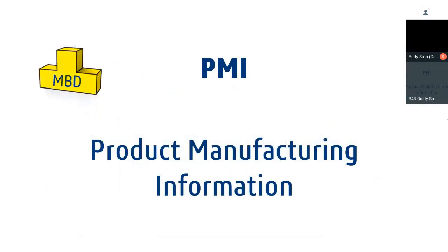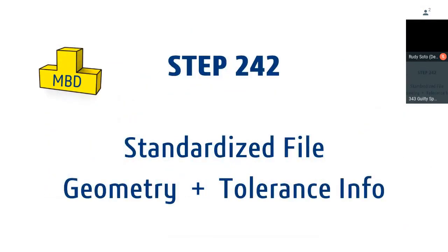So just some final terminology things here. If we're going to a format that is standardized, PMI is not unique to SolidWorks. For example, CamWorks, which I mentioned before, or Mastercam can read this STEP 242 and bring the PMI information in from it. In order for us to utilize this file format across multiple platforms, it had to be standardized, and this is what it became standardized as.